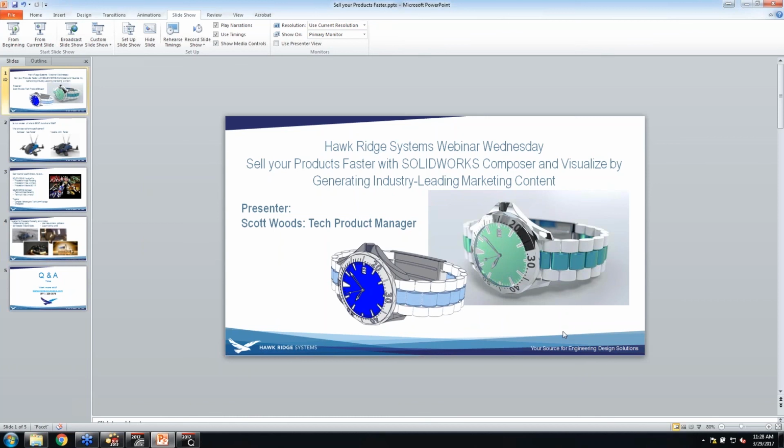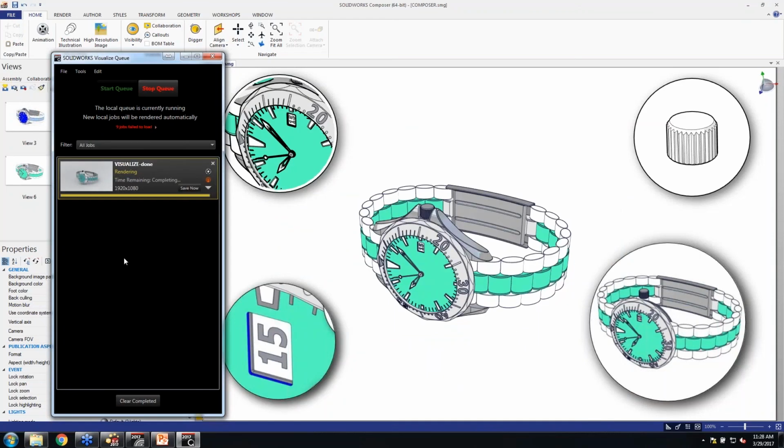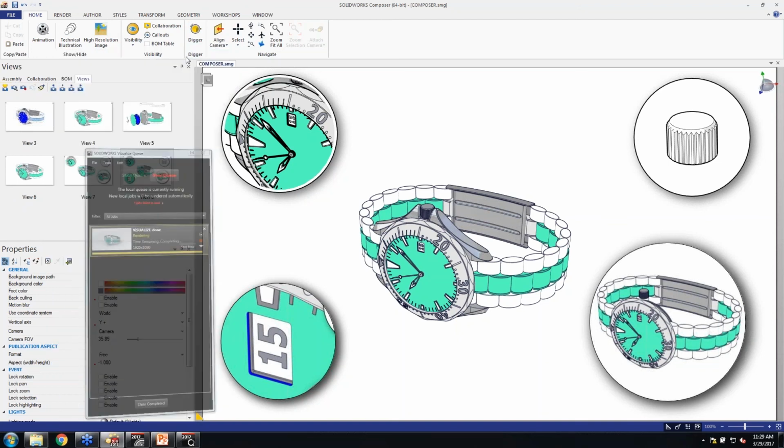And let's take a peek at that folder. There's our image. So that's the image that we just made in Visualize. It looks like I have it floating a little bit. I didn't catch that. There is a setting in there to snap the floor. You can also take the floor and bump it up, or you can take the model and kind of rotate it. So the problem is it's probably touching the back and not the front. So I take the whole model, rotate it just a couple degrees so it touches. But yeah, so that would be the way that is done, and it looks pretty good.